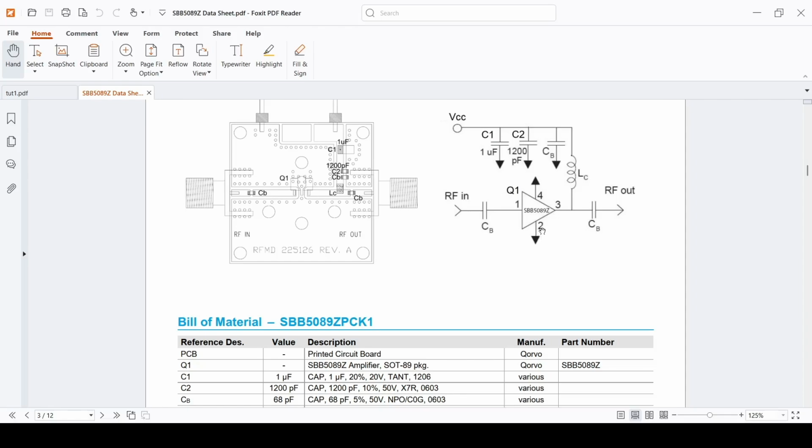So what we need to do is usually when we work at higher frequencies and we want to design a discrete amplifier, whatever components we use, we need to find their S parameter file from their providers, then add those S parameter files to our simulations, and using those, find the overall S parameter of the amplifier. So if we use a capacitor in the main chain, we need to find its S parameter file. Also at the output, we need to know the S parameter file.